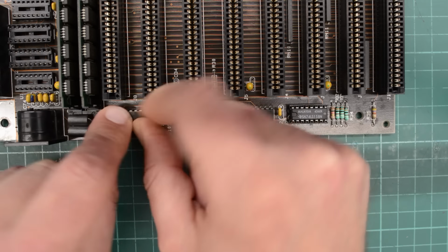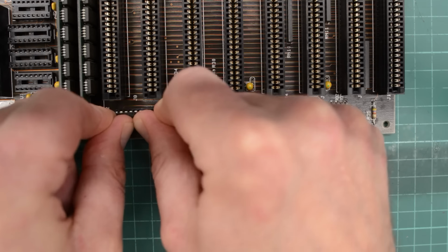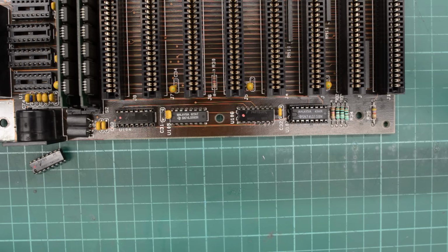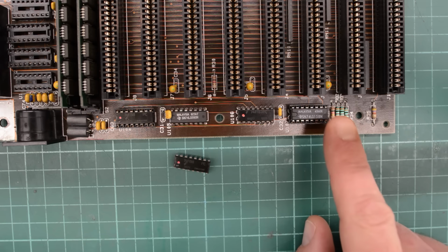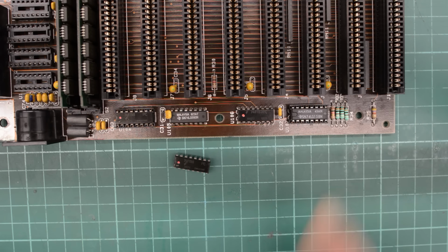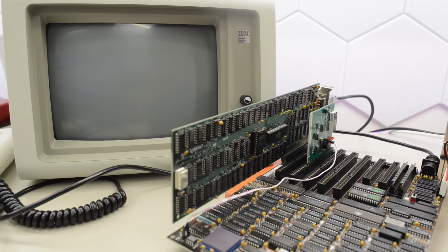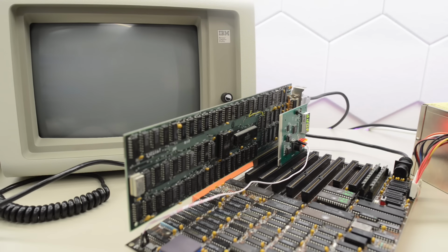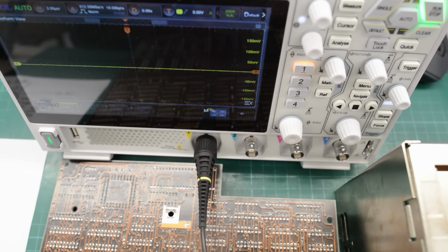You're gonna need one of these if you want to hack your XT board to take 640K directly on the motherboard. Well, they are not likely to be bad both, so I have reinstalled one of them in the socket and a brand new chip in this socket here. Okay, fingers crossed. No, same result. Okay, I swapped the two chips. Let's see if this chip is bad. No, no such luck. That chip is probably good too. Okay, my guesses were wrong.